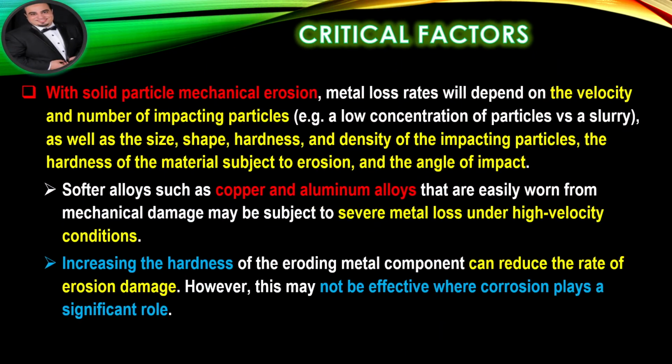Critical factors. With solid particle mechanical erosion, metal loss rates will depend on the velocity and number of impacting particles, as well as the size, shape, hardness, and density of the impacting particles, the hardness of the material subject to erosion, and the angle of impact.